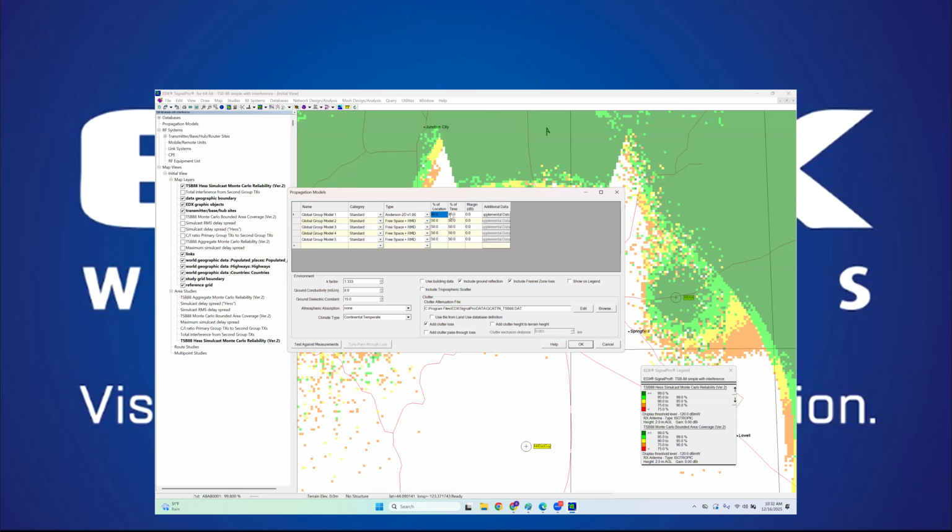If I do that, I'm applying fading to the propagation model itself, so the predicted signal levels will always be lower than the direct path prediction gives us. In that case, we could be under accounting for potential interference.